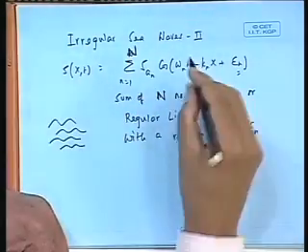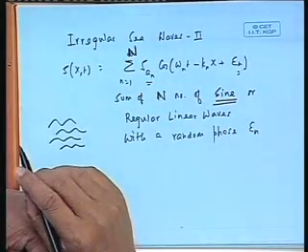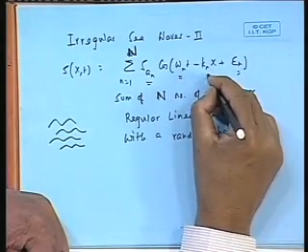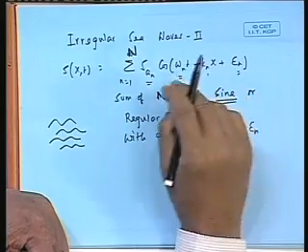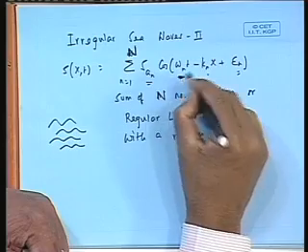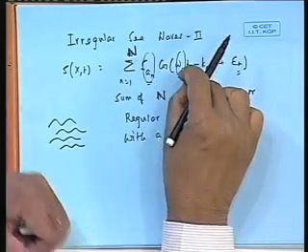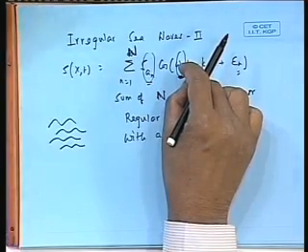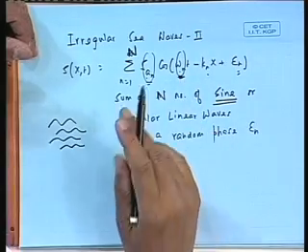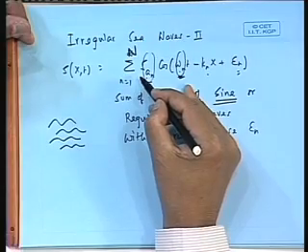Now, if you look at that, you will see that this has got the amplitude part. This has also got the frequency part. k is after all connected to omega, because omega squared is gk. Therefore, these are connected. So both informations are embedded. Supposing I took a random signal and could find this together, then I will know for which omega what was my corresponding xi a.